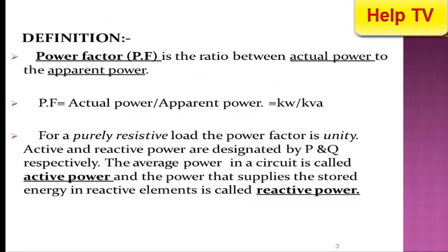Conclusion. Definition. Power factor, P.F, is a ratio between actual power to the apparent power. P.F equals actual power / apparent power, equals kW / KVA. For a purely resistive load, the power factor is unity.